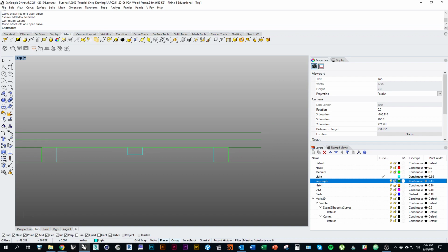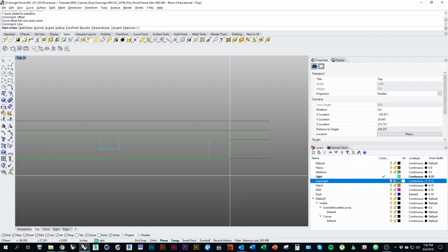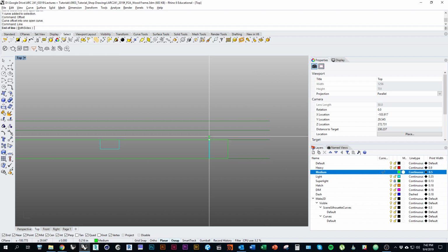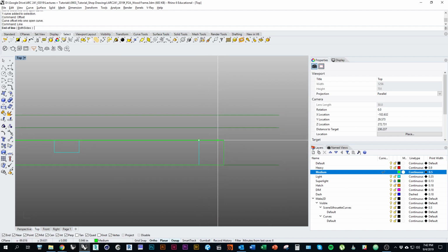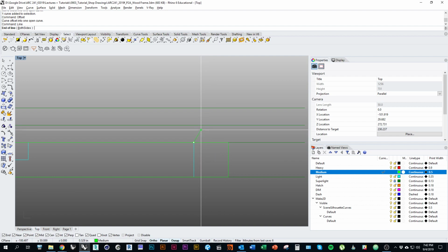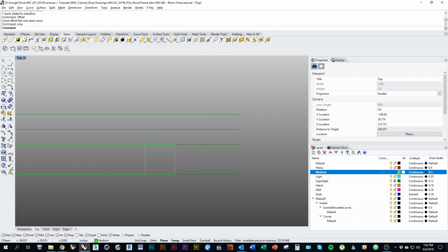And then what I want to do is actually start to draw this thing in oblique, elevation oblique. So I'll type in the command line, change back to medium. I'll snap from this point, from the inside of one of my joints. Now I can hold shift to snap to a certain angle, in this case 30 degrees, and draw my line straight up to my next construction line.